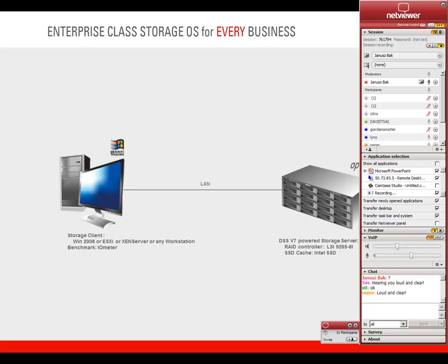SSDs have a known problem that the flash cells are able to get written only a limited number of times. So it is very important that the drive has a special chip which is doing proper wear leveling, meaning always writing the data into new space and managing this properly, so that the data are written equally in all cells. Because of the quite big capacity, you can get a very good write endurance, even for more than 5 or even 10 years.